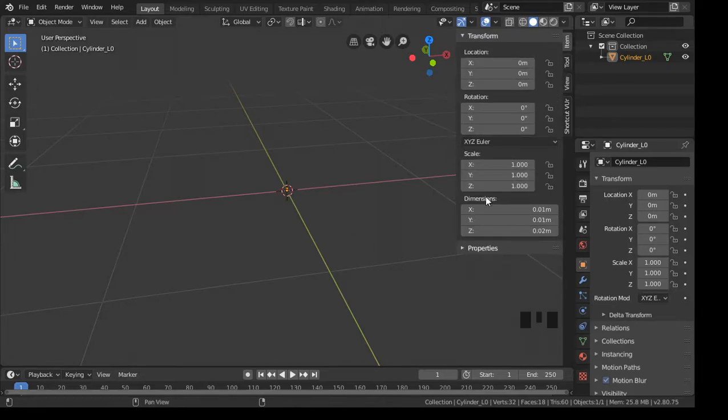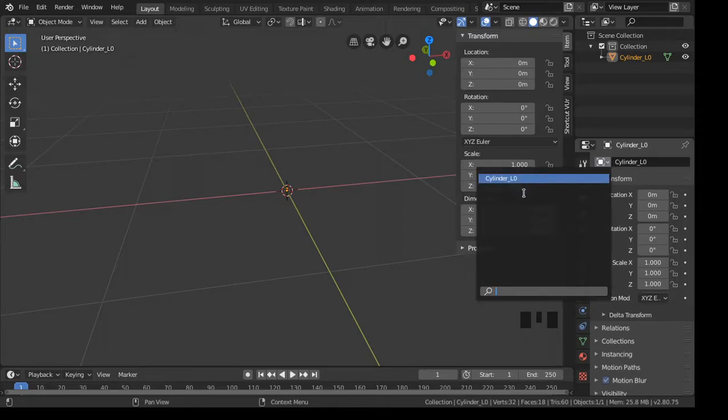And then go into item to see your transforms. But you can also see your individual items in your scene's transforms right here. And if you have multiple objects, you can change them here. And that'll be important when we go through the aspect of looking at how to get animations to work in TMTK for 2.8, because you'll want to be able to see the rotation on your armature versus the rotation on your individual meshes to make sure that the meshes are zeroed out, but the armature is not.